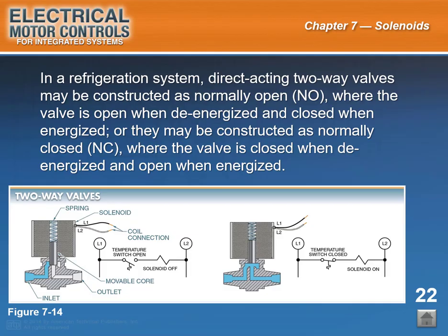In a refrigeration system, direct-acting 2-way valves may be constructed as normally open (NO), where the valve is open when de-energized and closed when energized, or they may be constructed as normally closed (NC), where the valve is closed when de-energized and open when energized.